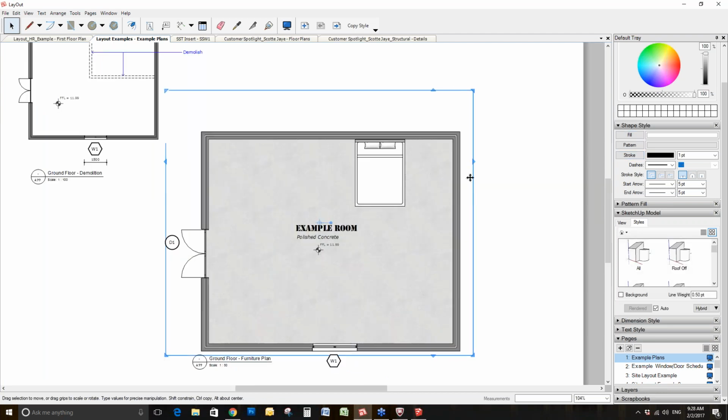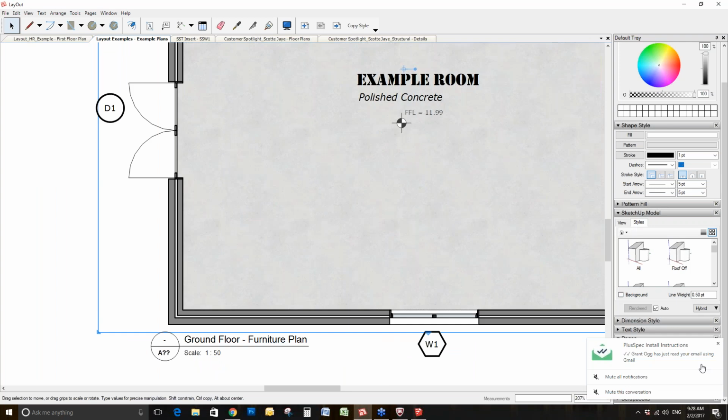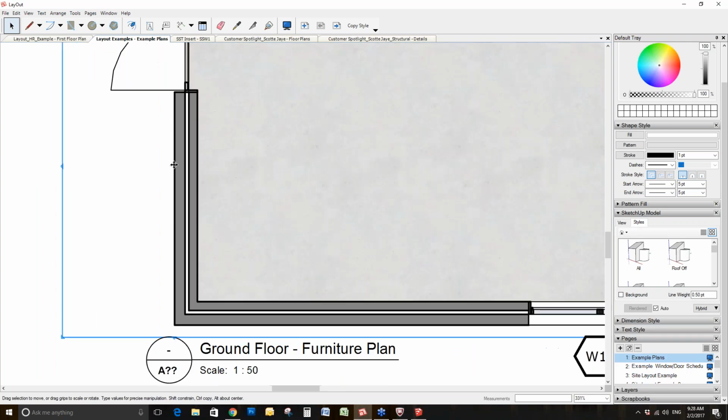When you click on the model reference, you're able to go into the SketchUp model, go into the styles, and in the styles you're able to see this line weight, and this represents overall line weight. So at this particular scale, I could decide that the line weight is not reading as heavy as I want it to, so I can actually add to it. So I might go to a 0.7, for example.